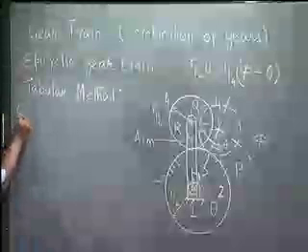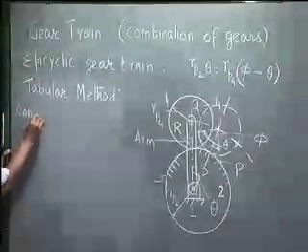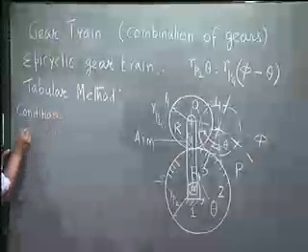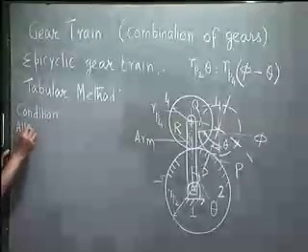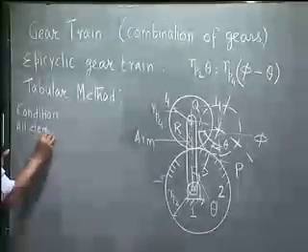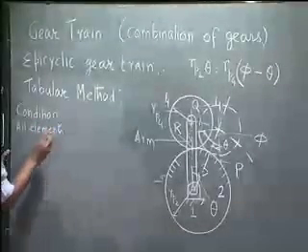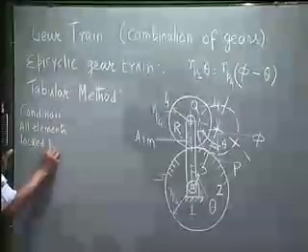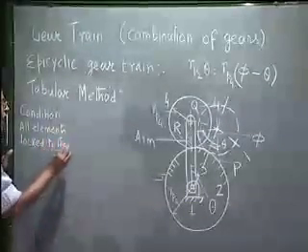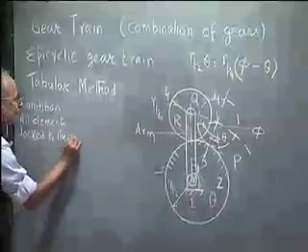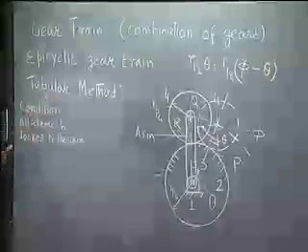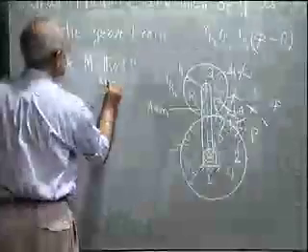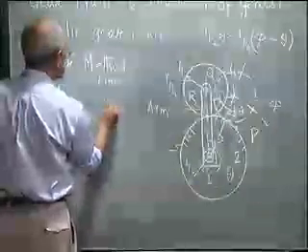And we write the condition: all the gears locked to the arm, which means the whole chain becomes one rigid body, and then give the arm some y revolution.